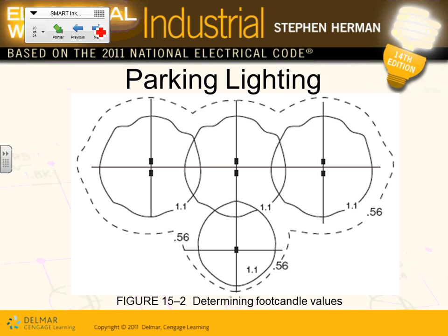Then when you have a parking lot, my friend, does that look familiar? You put in all your parking lot, you put all the cutoff. They're cutting at 1.1 here. So this area will be lit from 2 fixtures. You allow them to overlap. Remember how we did Visual? A little bit of overlap in each area. That's typically how we do it. And then we calculate the average or the minimum in the area based on the considerations that we have. Any comments, any questions, guys, about dropping your fixtures and having nice footcandle curves laid out to cover the area that you need?